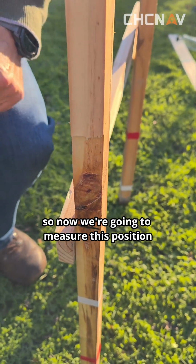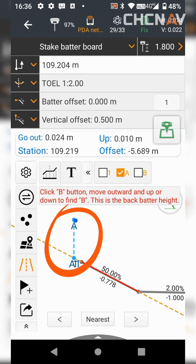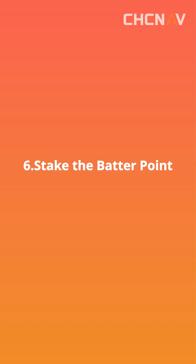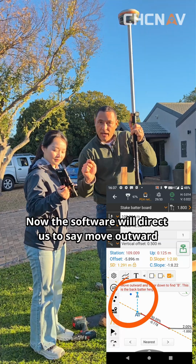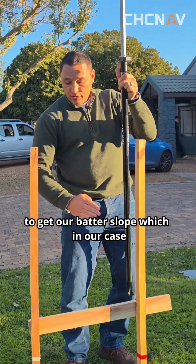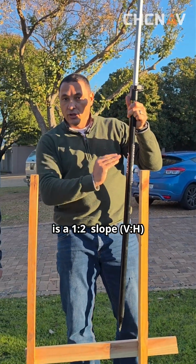So now we're gonna measure this position. All right, so we're now at the right height. We confirm we are at the right correct height. So we measure again. So now this is step 3. Now the software will direct us to say move outward. That's the road. We move outward from the road and up to get our better slope, which is in our case a 1 in 2 slope.